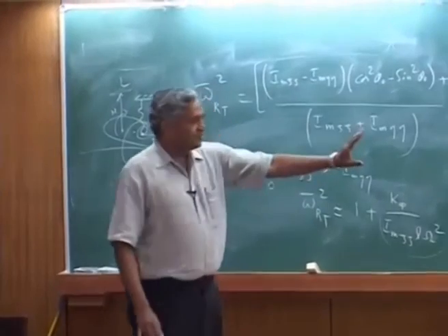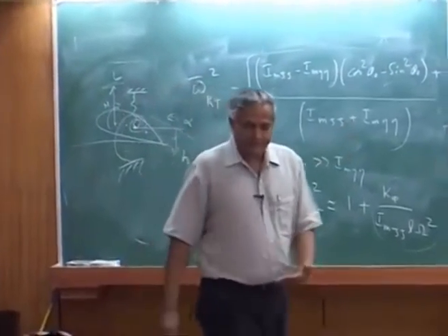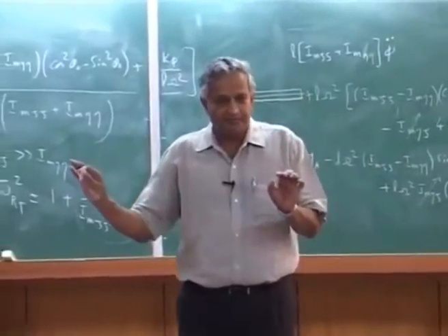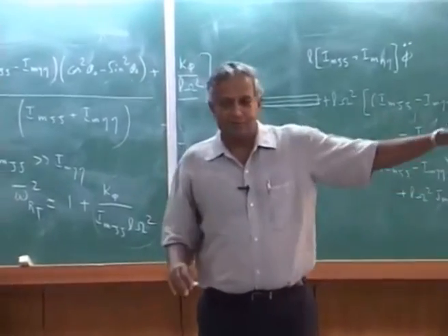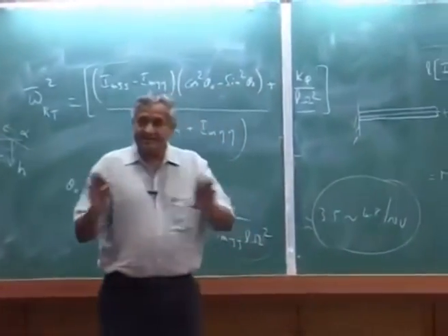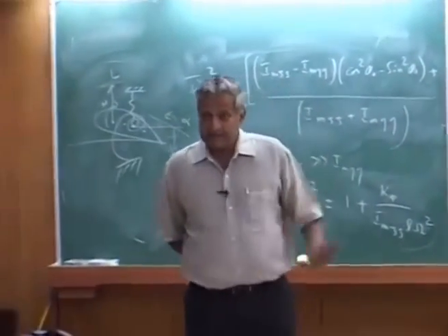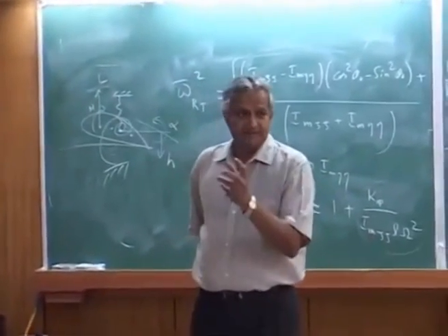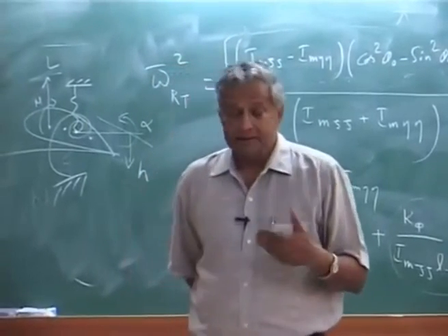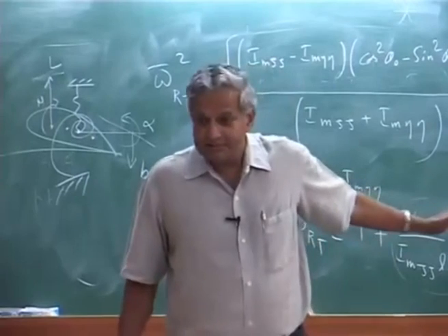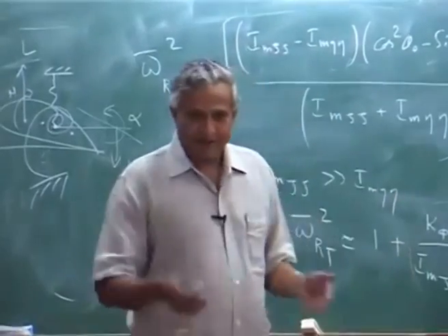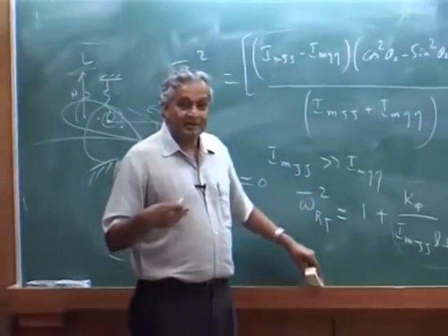What we have shown here, in the first level, I would call helicopter dynamics the first level part. You learn isolated effects, you see what each blade does in flap motion, lead-lag motion, torsion motion. And then you know the frequencies and what range they are in. These are all isolated motions to understand what influences the frequency. Now you have learned up to this, next what? That is where we build the subject.